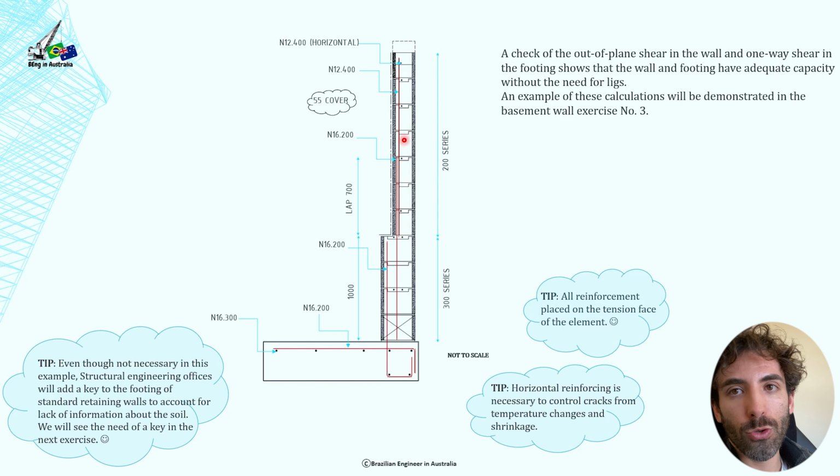You probably calculated that by yourself just to make sure that works, right? I know it works, but just do a quick calculation yourself for training purposes. And what else? The starter bars here, we just matched with the reinforcement of the wall. So we've got starter bars which are N16 at 200 as well.